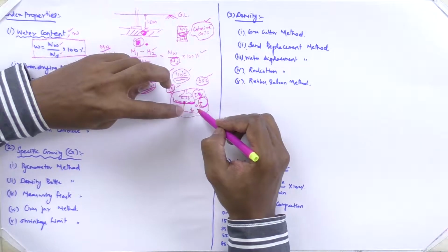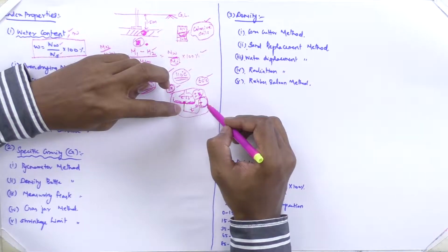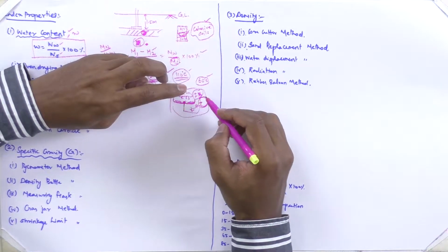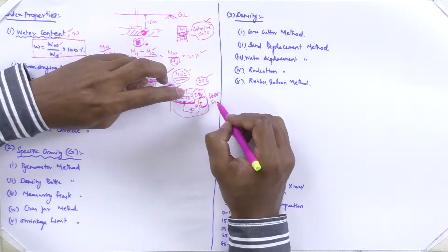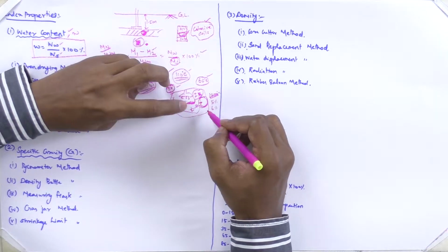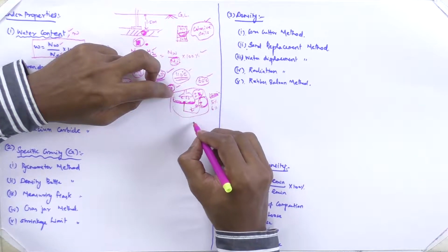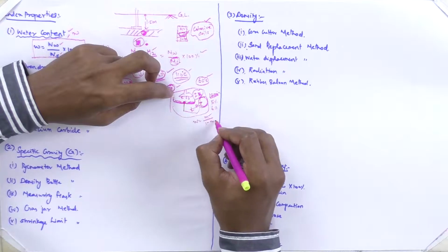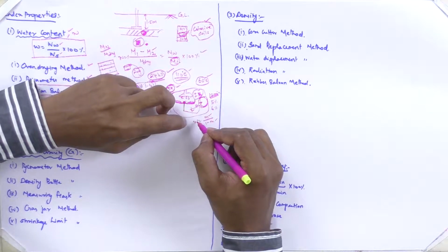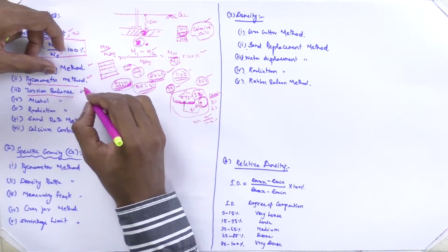Like a torsion balance, with a spring attachment, it goes upward and shows a reading. At the end, say after 10 minutes, you get a direct reading of 5% or 6%. It has to be corrected further. How? Water content is m divided by 1 minus m. The moisture reading is not the final answer, so it has to be corrected like this.